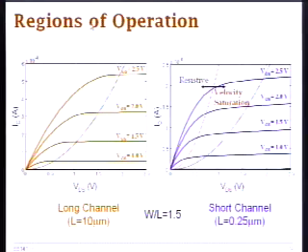So this is a comparison. You have more current from your long channel device than in the short channel, and we are comparing a device in the same technology for the same W/L ratio, except that the channel in one case is 10 microns, in another case is a quarter micron channel. And then we see the difference between these curves. You have more current because of this quadratic spacing in VGS, and in the short channel we have early saturation, that's velocity saturation.